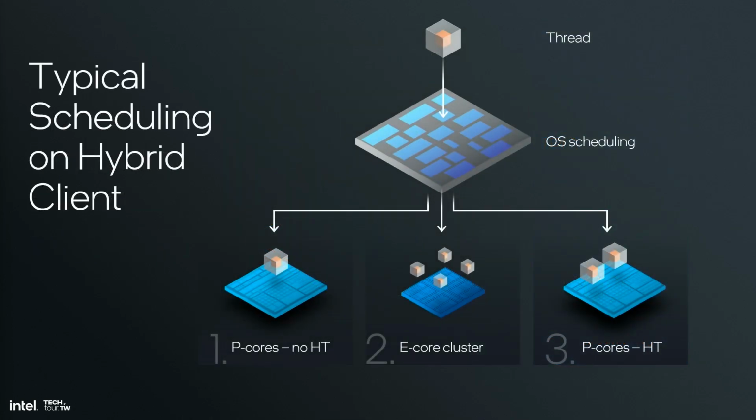However, the introduction of hybrid compute and client, where E-core clusters are bundled together with P-cores on the same SoC, shifted the paradigm, as E-cores provide a much more efficient and performant multi-thread acceleration vehicle than hyperthreading. And as you know, OS scheduling priority really demonstrates this, where in scenarios where performance matters, threads are first scheduled on the P-cores and then on the E-cores.